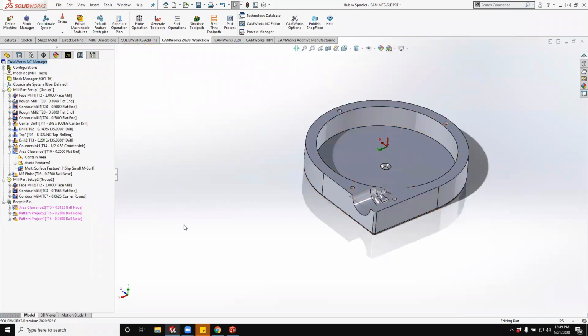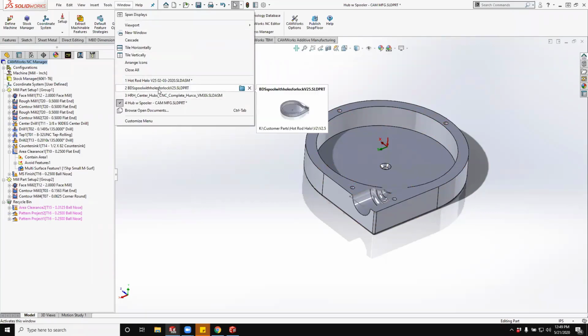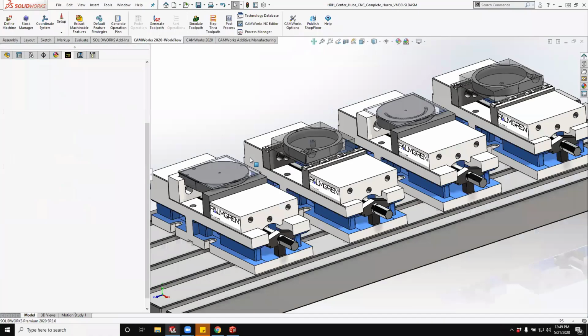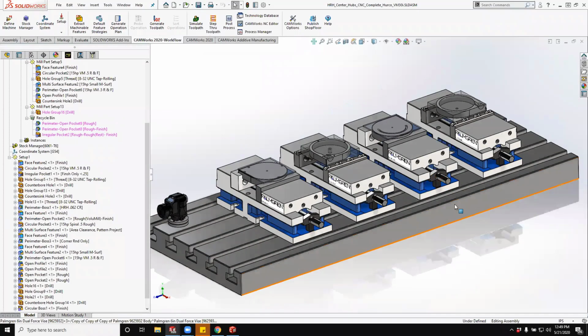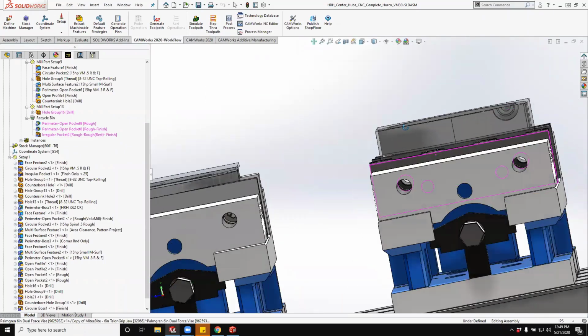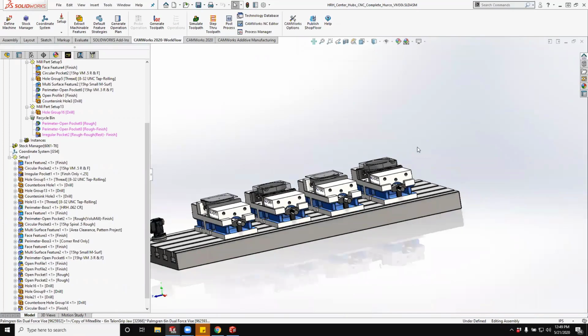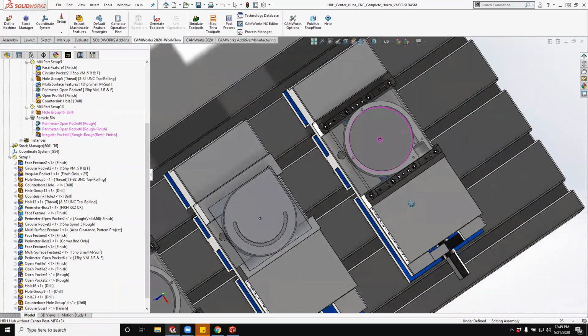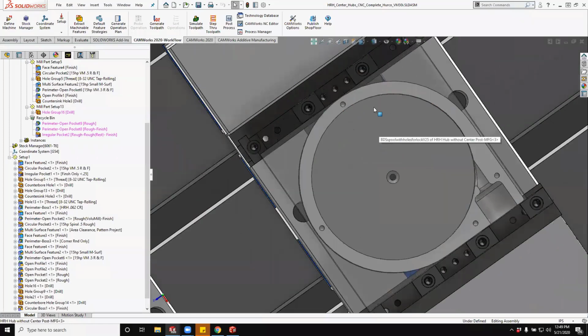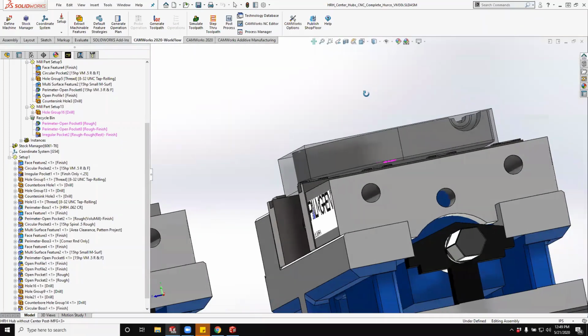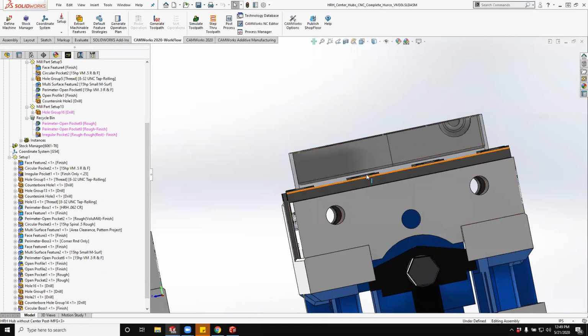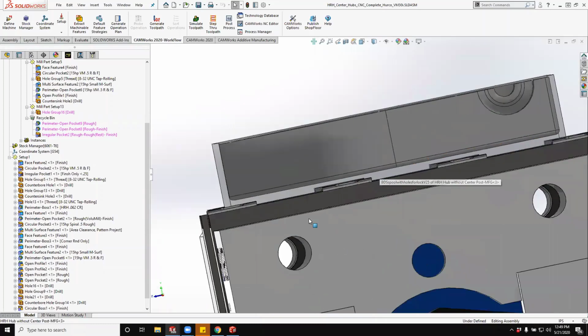All those capabilities would be in the CAM Standard package. And then just as a final quick overview, what we're doing as we run them, we'd be running them with more of the SOLIDWORKS CAM Professional capabilities. And here, Brian has done a great job of modeling up all these vices. These are our Mighty Bite clamps holding that thing in place. And the great thing about being in the assembly environment is we can see where our clearances are. If I look at my Mighty Bite clamps, I can tell that I've got plenty of clearance down to the bottom of that part.